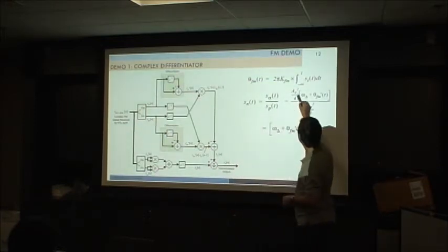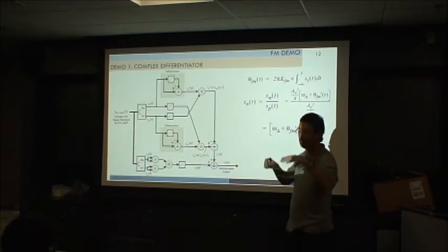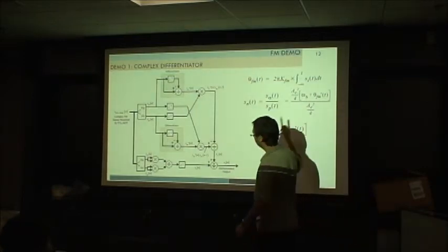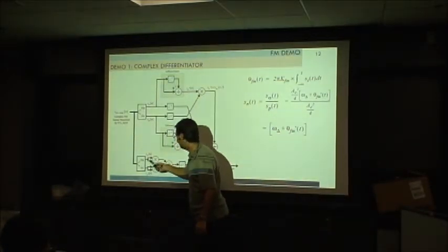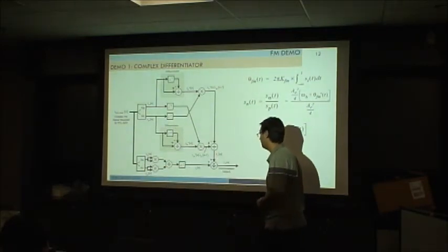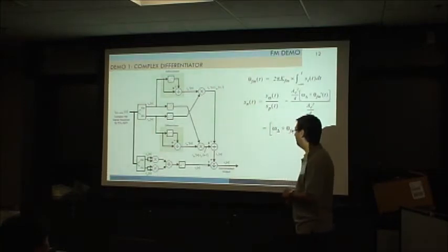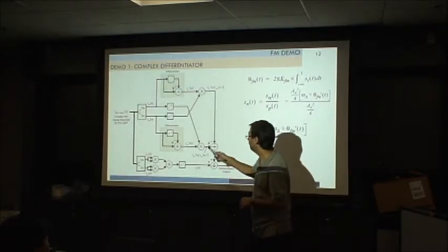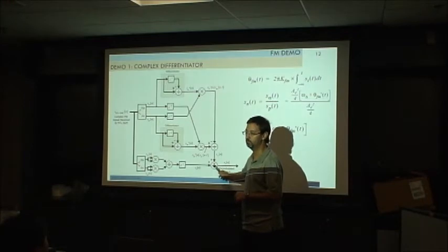But what happens is that we have this factor that will be like a DC component, so the recovered FM signal will look something like this, okay? And we want this signal to be here, okay? So that's why we have to normalize in some way. In order to normalize this guy, we just square and take the magnitude, basically. This is a way to take the magnitude and just divide there. And you say, oh, okay, this could work fine, but as you could see, this is quite simple, but it is not as simple to implement in hardware.